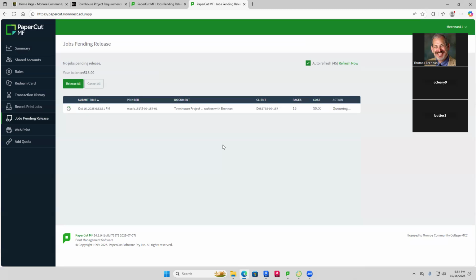Actually, it did. Just go ahead and turn it on. Hit that blue light bulb. Okay, and then you've got to light up, so just click on any one of them. Then right click your mouse and choose unhide view category. And then turn the yellow one back to blue, and then they all are. Take your pick. What happens is when you're getting it finalized for the project, you turn them off. I left them turned off, but when you're working on it, you have to turn them on. So just a little addendum.